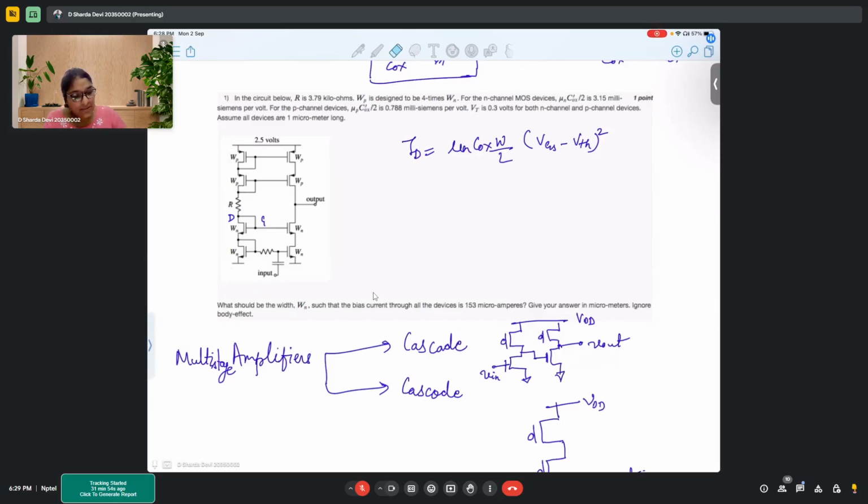So starting with this particular problem, you can see that there are mirror circuits. One thing to keep in mind always is when you see transistors stacked in series, a single current will flow through the transistor. Depending on that, how your things change, that's how the final outcome will appear. So it's a rule of thumb that when the transistors are connected in series, all the transistors will carry same current.